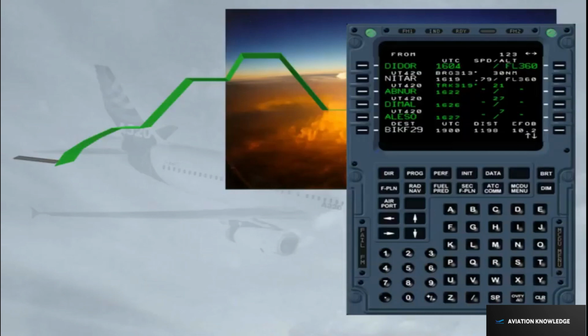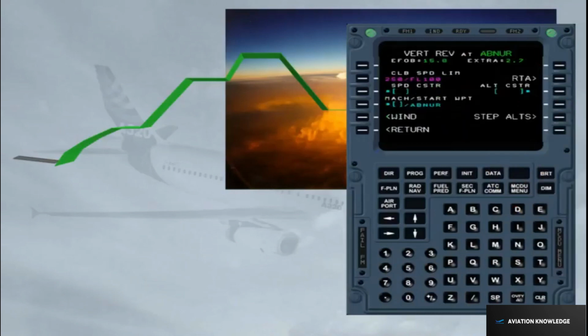The vertical flight plan includes vertical constraints assigned at waypoints, altitude and/or speed, which are stored in the database and entered manually by the crew. Another constraint, the requested time of arrival, or RTA, at the revised waypoint may be entered by the crew. Also part of the vertical flight plan are constant Mach segments, defined by a desired Mach value and its associated starting point.